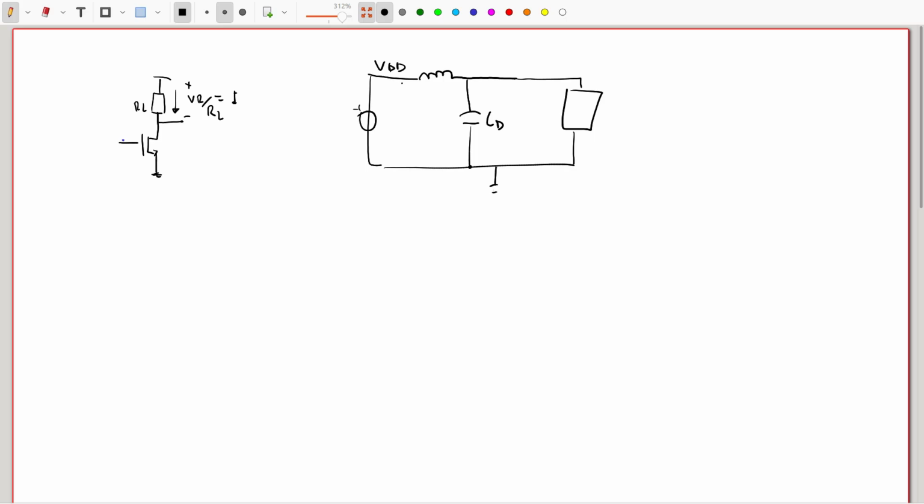So if there are circuits that are more inductive, and there is another circuit here around. So if there is a lot of activity, for instance digital activity happening far away, that is changing the currents in these circuits, then the decoupling capacitor will hold the voltage.